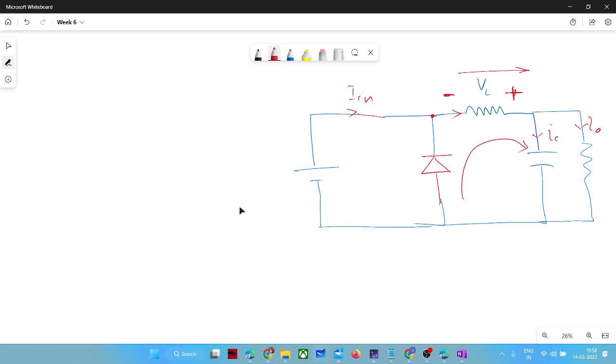You mean to say current is falling now? Current is falling, and when current is falling through the inductor, it means it is discharging. And when it is discharging, we studied in transient analysis of circuits that when an inductor discharges, it has become the active element. Whenever any active element is there, since resistors are considered passive elements, its drop we denote like that. If any voltage source is connected to that element, current enters from the negative polarity, and if any passive element is there, current enters at the positive polarity. That was very basic from circuit theory, so that's the whole funda we can apply everywhere.